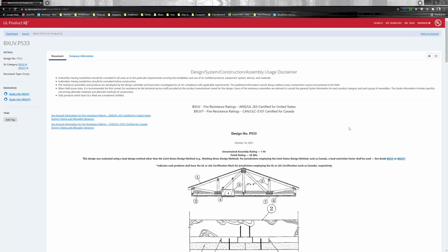That's why you see Underwriters Laboratories ULs for all these rated assemblies, almost certainly stuck in an architectural drawing package. They want to be able to prove, or shift the liability away from themselves onto Underwriters Laboratories and the contractor, that this wall is going to perform in a certain way and resist fire for a certain amount of time.